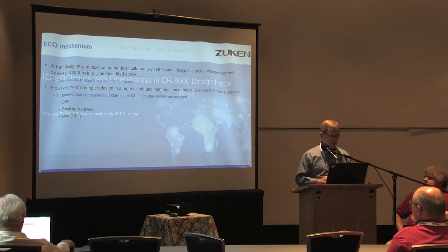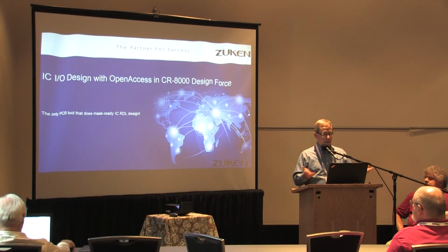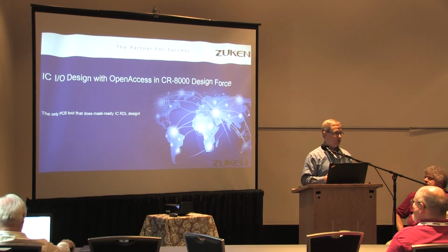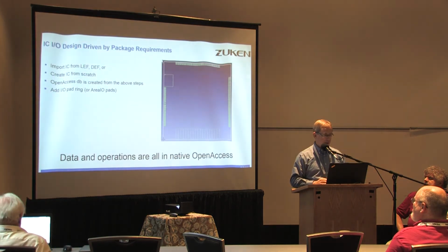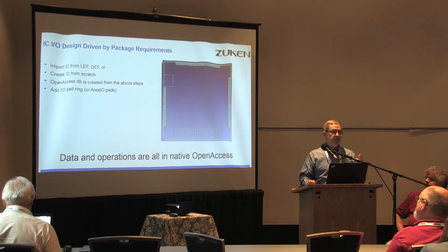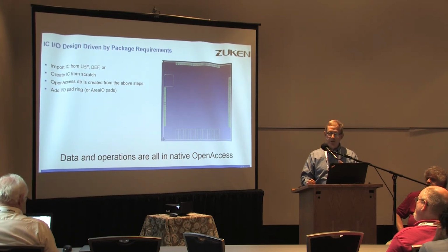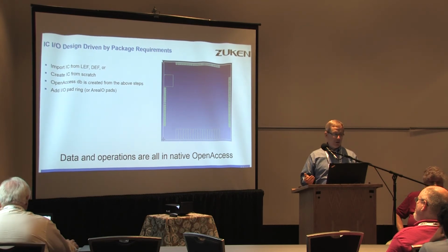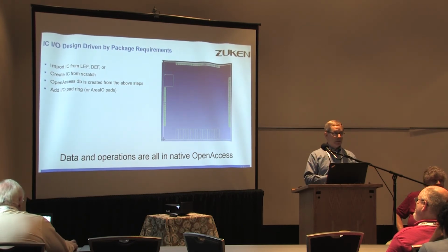So how do we use this in Design Force? Let me just step through each of those steps that they showed in the movie, and then I'll wrap it up. First of all, one of the key parts of this is that it is bidirectional in how we design between the die and the package. IC I/O design can be driven by the package requirements, or vice versa. We can bring in a fixed die and drive out to the package. We'll import an IC from LEF/DEF, or you can create an IC from scratch, and then that will create an OpenAccess database from these steps.